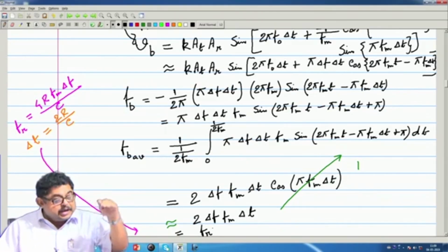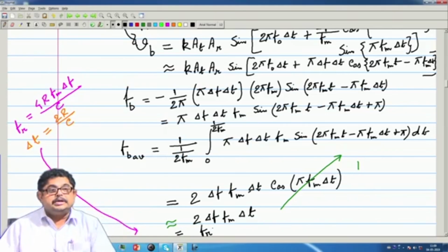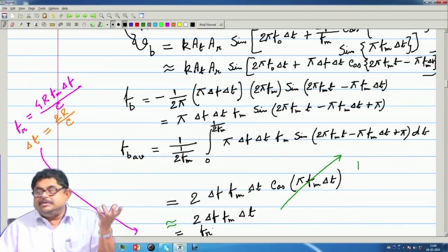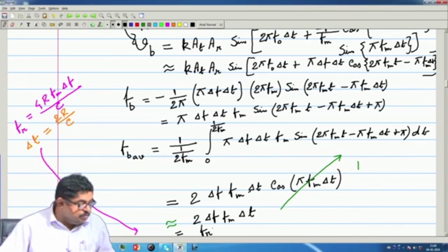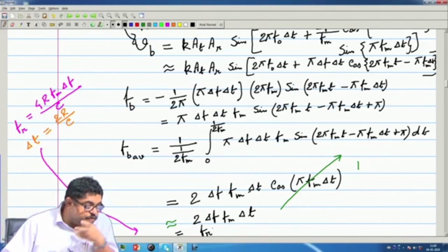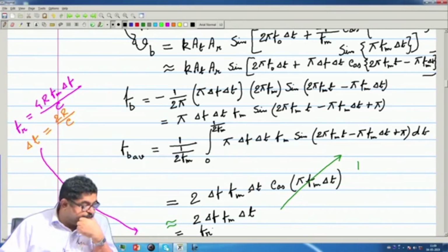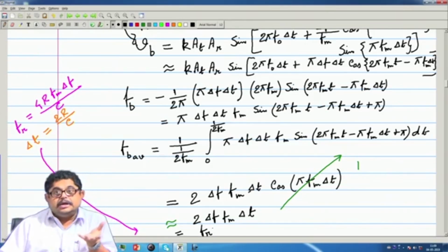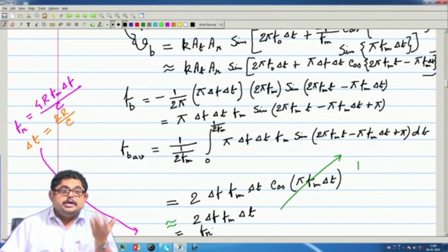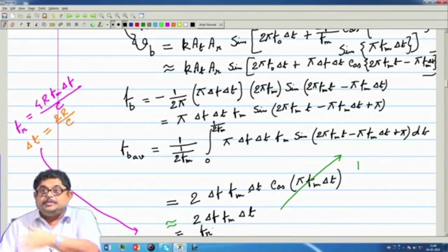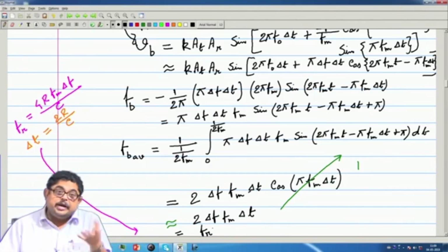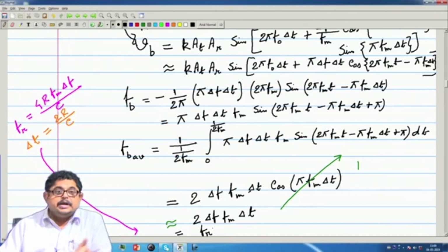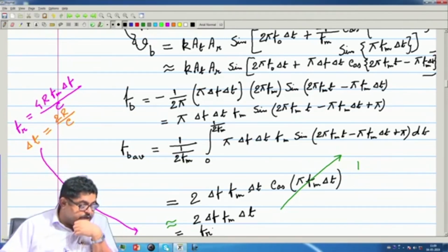At that time the ground is the target. It is sending a continuous wave signal, frequency modulating and receiving the echo. Also, you see that the RCS of the ground is a good scatterer at microwave frequency. Obviously, at various frequencies the RCS of the ground is different, but these radars operate at microwave frequencies. So, it has a good RCS.